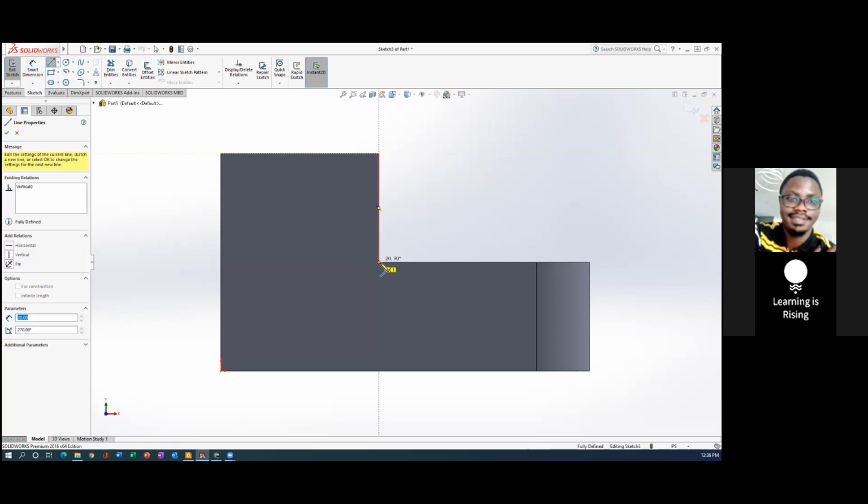Okay, so I'll go this way. You go up and make the line up. Yes, that way. Don't snap it to that midpoint, please. If you put it to that midpoint, it will automatically snap to that place. It won't be able to go out of it later. Don't put it at the midpoint. Just shift it a bit. If you put it at that point, it's telling you that you are at the midpoint. Any other place better than the midpoint is fine, because if you put it at midpoint, SolidWorks believes that you want to do half. So from here, we now complete. Yes, the last one.